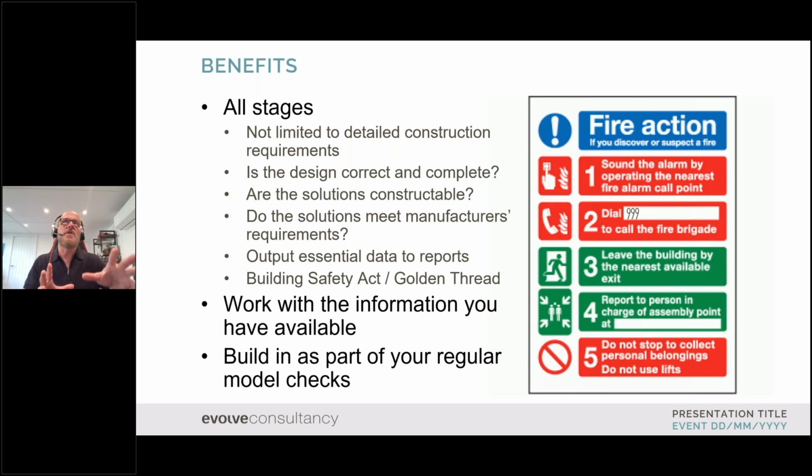But unlike what I showed you there, which is just a sample set, don't have them as a totally separate rule set. Build these in as part of your regular model check. So as you're going through and you're trying to identify, I don't know, whether there are 15 doors and whether they've all been named correctly, put these rules in there at early stages to get it part of your regular coordination exercise and design checks on your models. Keep it there and you'll get the best out of this that you can.